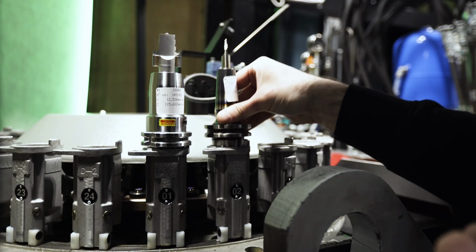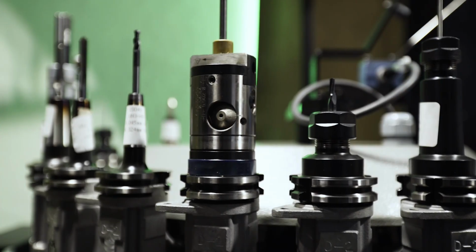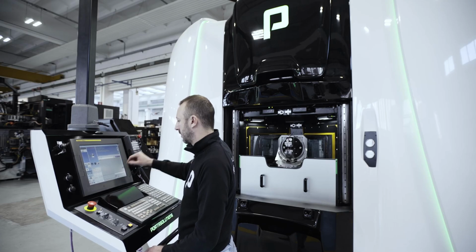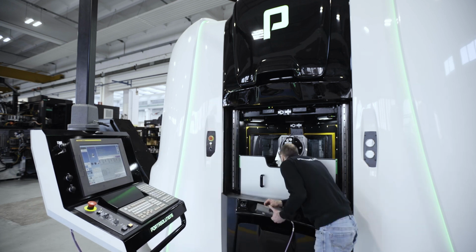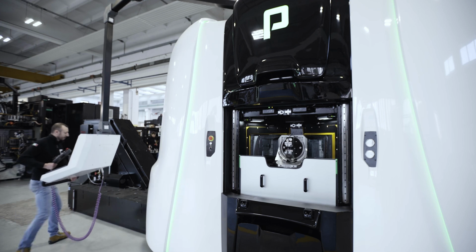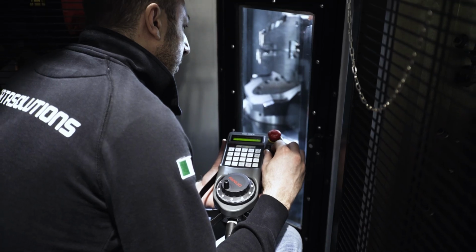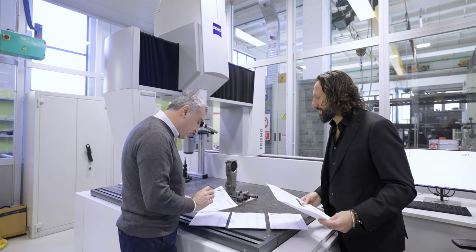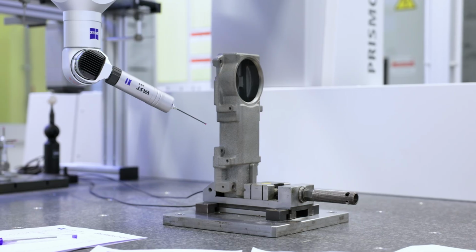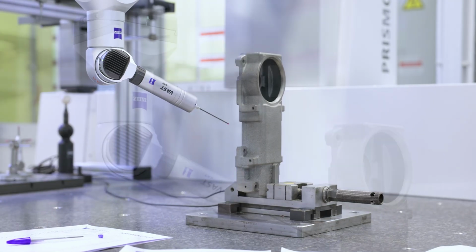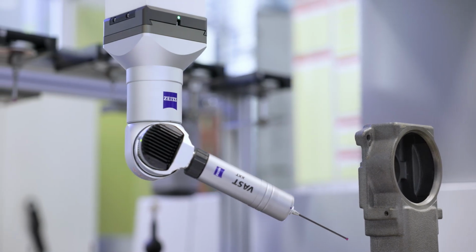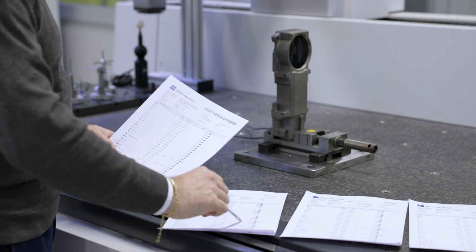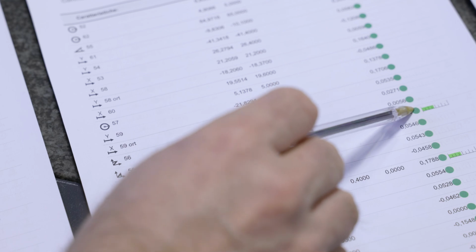We take all the information of step number two and we do a practical test on a real machine tool. So we tool the machine, we clamp your components, we machine it, we make chips, and we have a finished component. This takes us to step number four, where there is a performance check. In this performance check, we check of course cycle time, but also the quality of the part in terms of geometry, tolerances, and CPK value, so everything that is required to certify that the part is produced in the correct way.